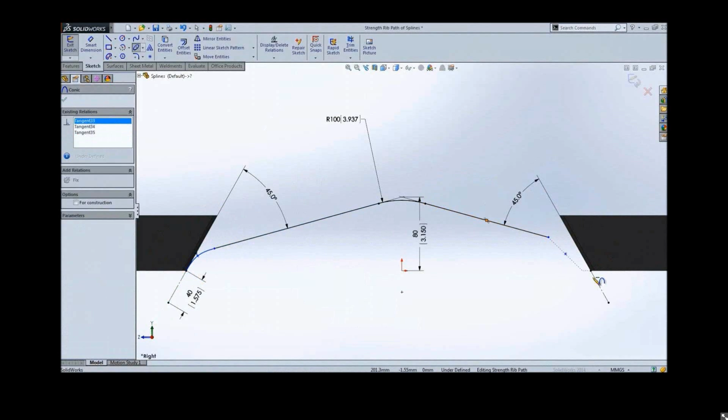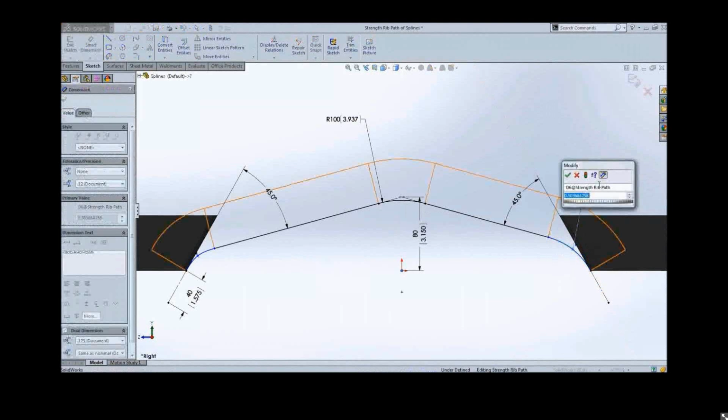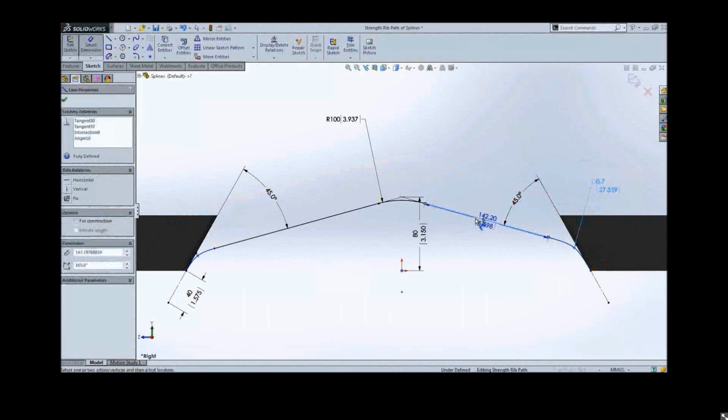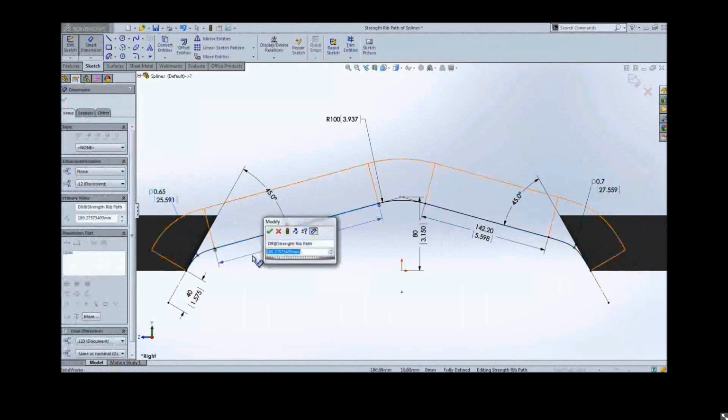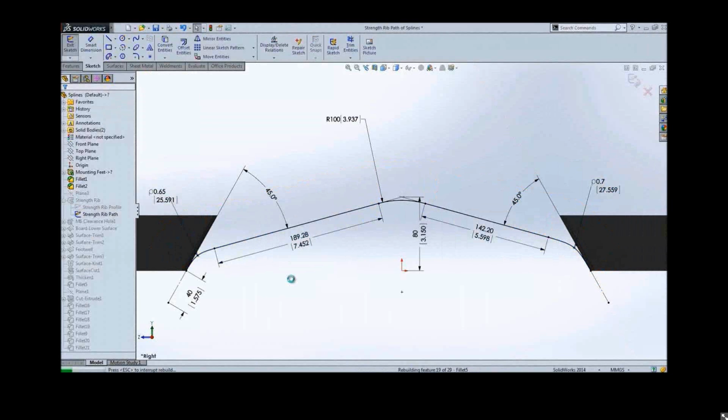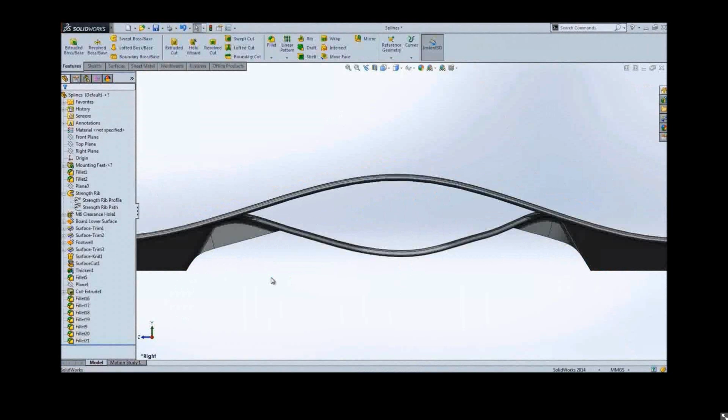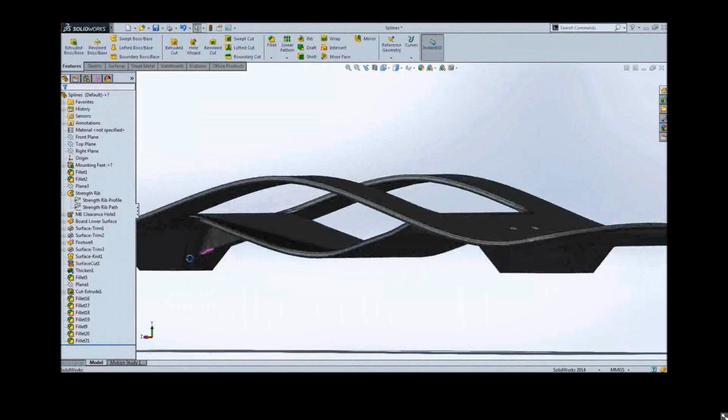As soon as you click a conic and insert it, it's automatically going to find all the tangencies for you to give you that nice smooth result. This removes a lot of steps from having to manually click and add those tangencies ourselves. All that we have to do after we replace it is dimension the conics again with a rho value or a radius value, and our sketch will update, and we'll now have this new conic, which gives a much smoother result in our sketch.